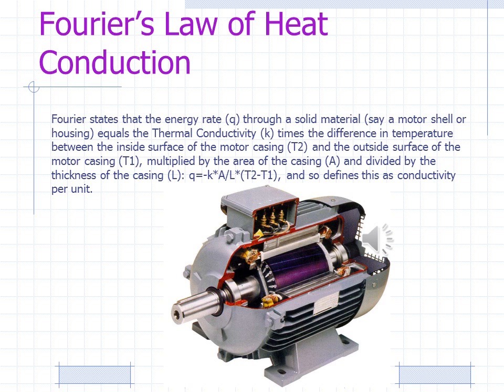The gap will insulate the rotor, causing the rotor to heat and radiate, then convect and radiate to the housing. The second law demands inefficiency at each step, and Kirchhoff does as well, and so causes a low heat transfer from the rotor to the air gap, then to the stator, and the stator partly to another air gap, partly via conduction to the casing.